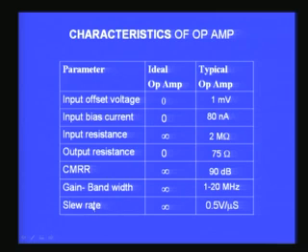So, finally, last is the slew rate, about which also we will discuss later. It is about 0.5 volts per microsecond in the case of the operational amplifier 741. So, I want to just give you this so that you get an idea of the numbers corresponding to the various parameters and the characteristics that we talked about.